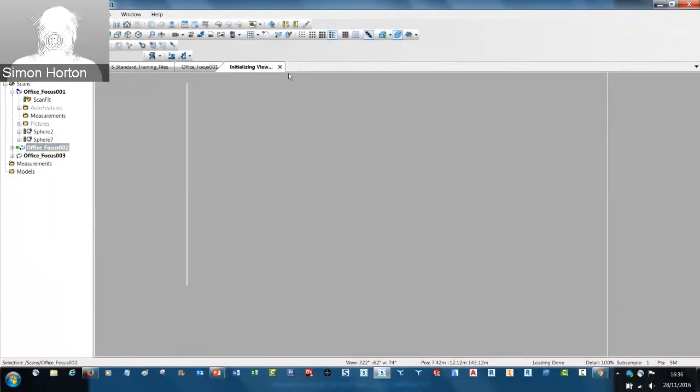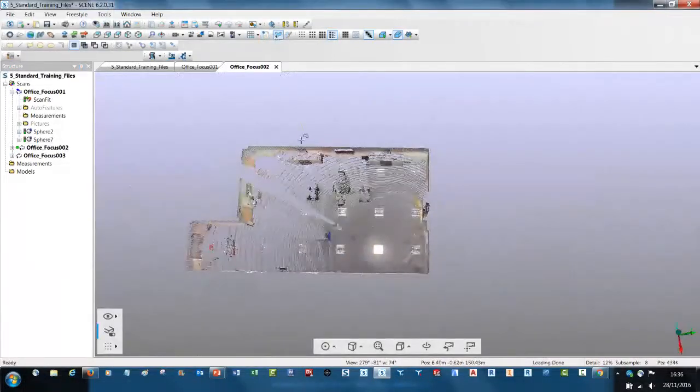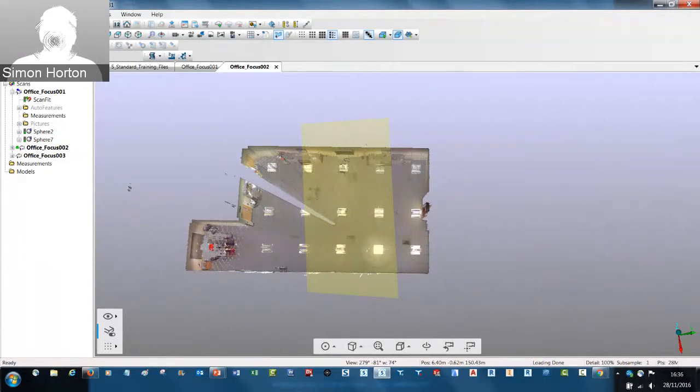So if we view that in 3D and place a selection box around the outside, as we would traditionally do with a yellow selection tool, as I right click, now we get delete inside or delete outside. That's because we've got the FLS file, the native file, loaded. As soon as I unload that, I go back to delete or invert in the same way.